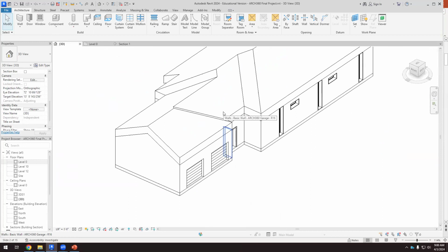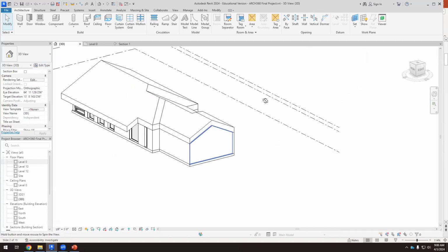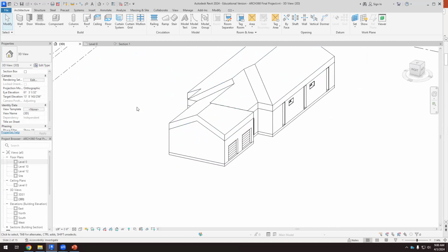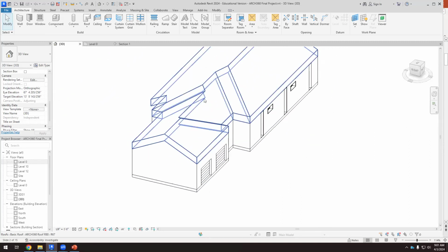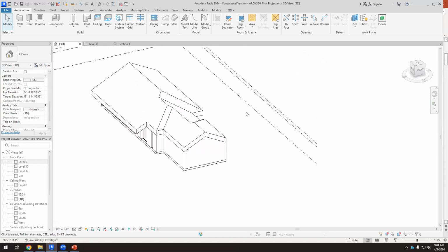Okay, so that's why I told you that sometimes we have to model a simplified version of the house, because from the energy point of view, the difference between this roof and a roof that has just 2 slopes, we probably can't tell the difference when it comes to the energy results, but Revit usually doesn't like this, and none of the simulation software likes this kind of complicated roof. Even professional simulation software tools that you have to pay thousands of dollars to get the license for, you end up simplifying the model, and sometimes you have to simplify even the tilted roof. So you have to create something like a rectangle.